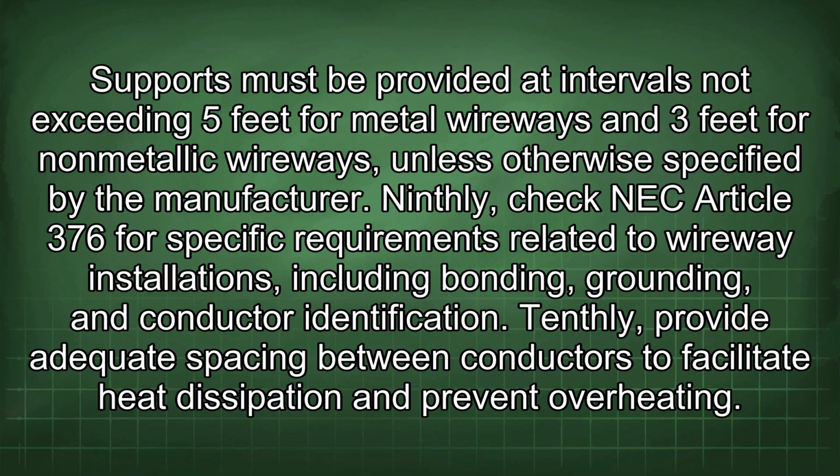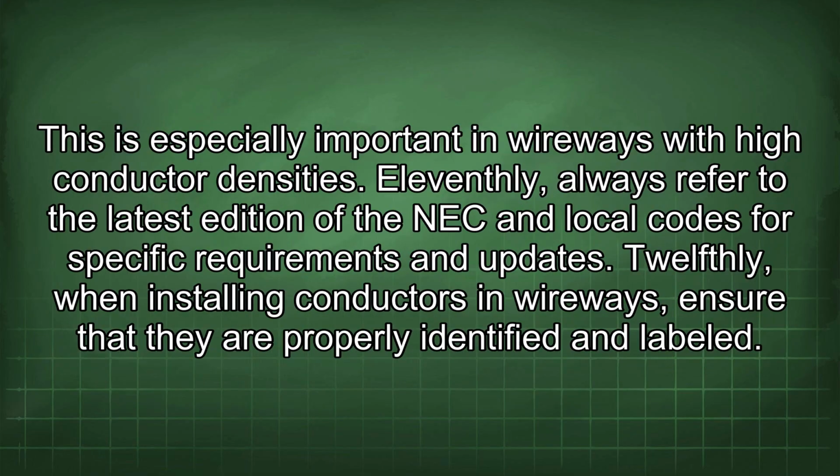Tenthly, provide adequate spacing between conductors to facilitate heat dissipation and prevent overheating. This is especially important in wireways with high conductor densities. 11thly, always refer to the latest edition of the NEC and local codes for specific requirements and updates.